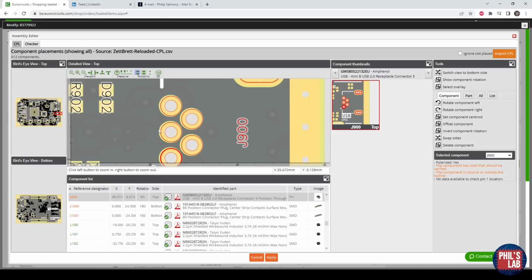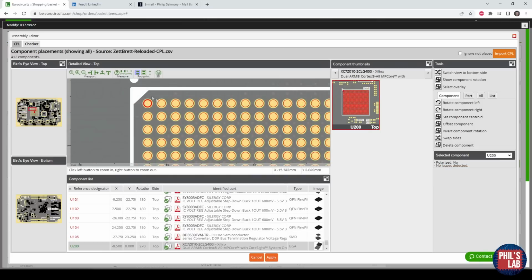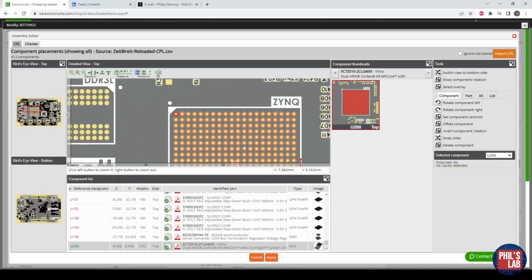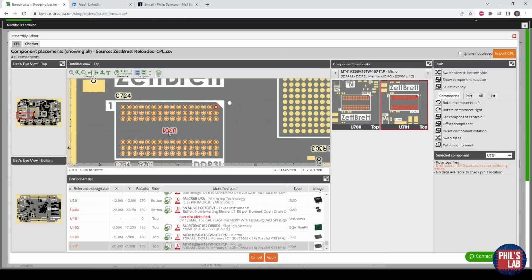This is especially useful also for through-hole parts. Also maybe for BGAs, clicking on them, I can see, is pad 1 aligned? Are the pads the right sizes? Did I mess up something with the footprints and so on? So this is something I'd highly encourage after you've generated the Gerber, bill of materials, and footprint placement files: upload it to their site, just to do another sanity or general check for your PCB design files and so on.